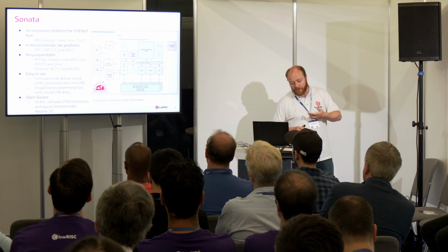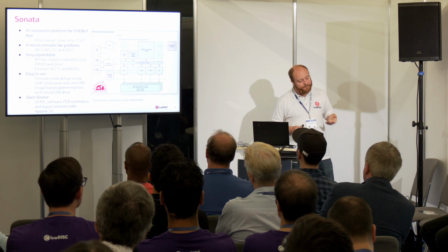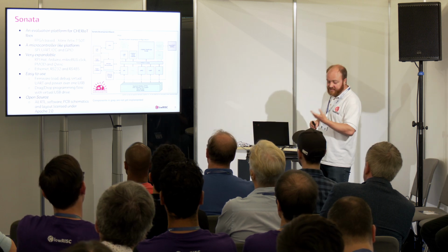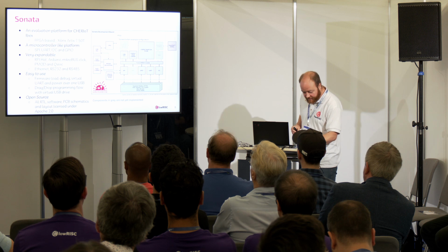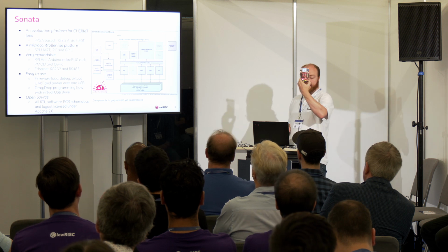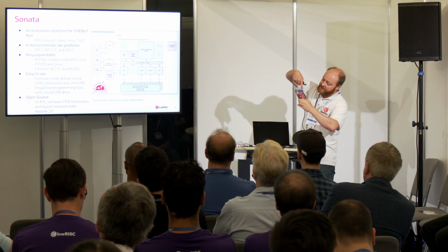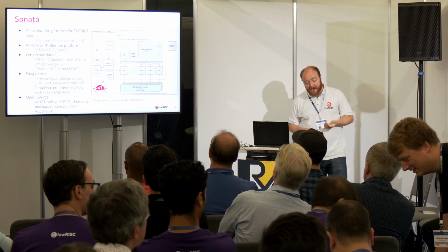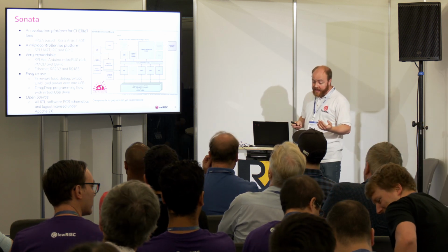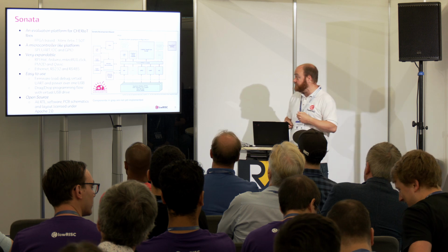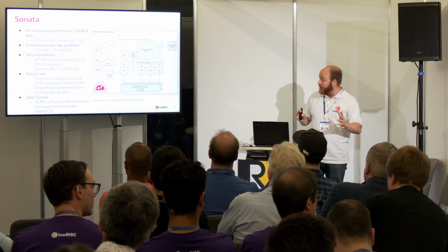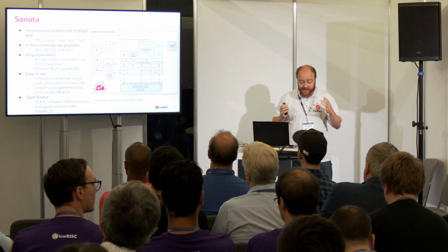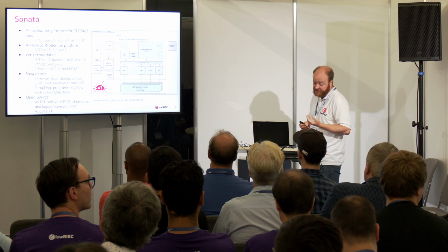So what it provides is a microcontroller-like platform. I say microcontroller-like because this fundamentally is an FPGA platform. This, by the way, is the board running some software right now, and there is an FPGA in the middle of this. It's very expandable. There's a whole bunch of different headers on there, and you've got Ethernet, RS-232, 485 serial, and various other things, so you can use it in a lot of different application areas.